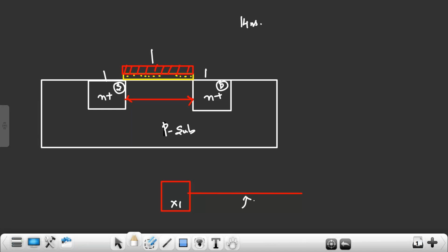So you have a net, and this net has a driver. Driver means the cell connected to its output. This cell is called the driver. Find its driver and upsize it. If its drive strength is x1, upsize to x2. If its drive strength is x2, upsize to x4. If x4, upsize to x8. Whatever drive strength you have, upsize to the next level.